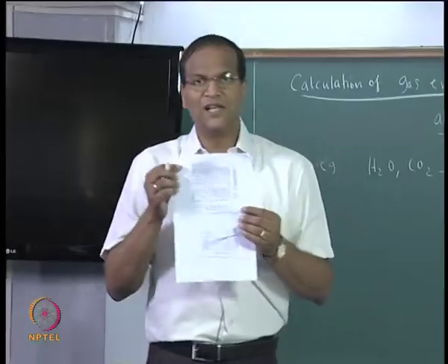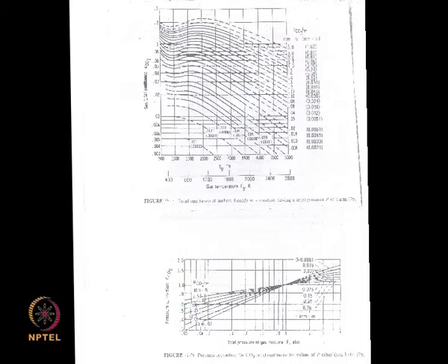Okay, so it is like this. The product of mean beam length into pressure is given in both FPS units and SI units. On this chart, Abhinandan, you have the chart or? I do not have an extra chart. You can share. Okay, so you can see that it will give you straight away the gas emittance. The maximum is only 0.3.